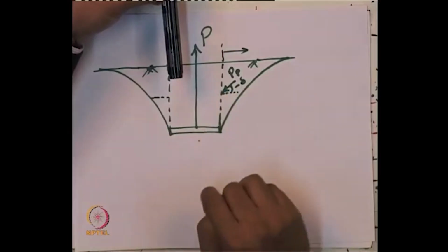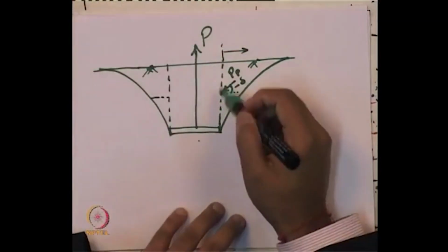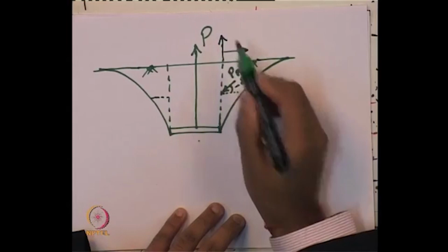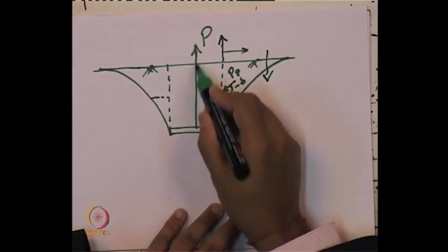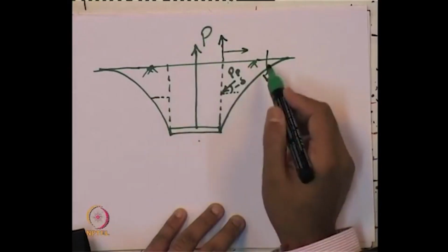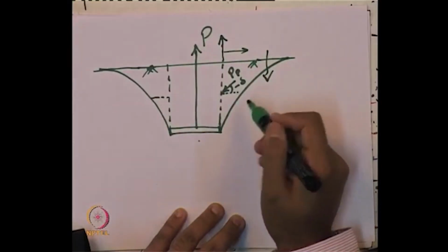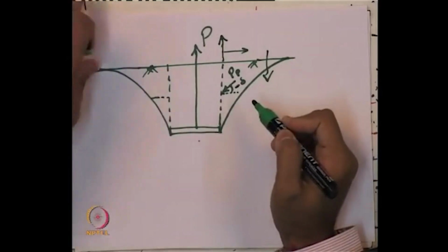And why do we call it negative delta? Because in this case this wall moves up and this surrounding soil moves down, because this entire central area goes up, this goes down. Clear? So, that is referred to as the negative wall friction angle case.